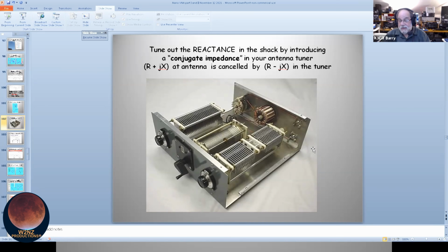Now more power is aiming towards the antenna. It doesn't make the antenna any better at radiating. The antenna still has the lousy SWR. But it takes the reflected wave and reflects it. And what does my transmitter see? 50 ohms. My radio is happy. It thinks it's operating into a 50 ohm dummy load, so full power. That's kind of magic. How does this work?